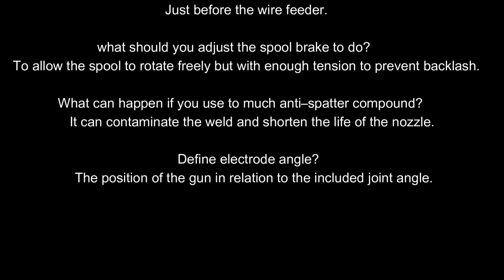What should you adjust the spool brake to do? To allow the spool to rotate freely, but with enough tension to prevent backlash. What can happen if you use too much anti-spatter compound? It can contaminate the weld and shorten the life of the nozzle.